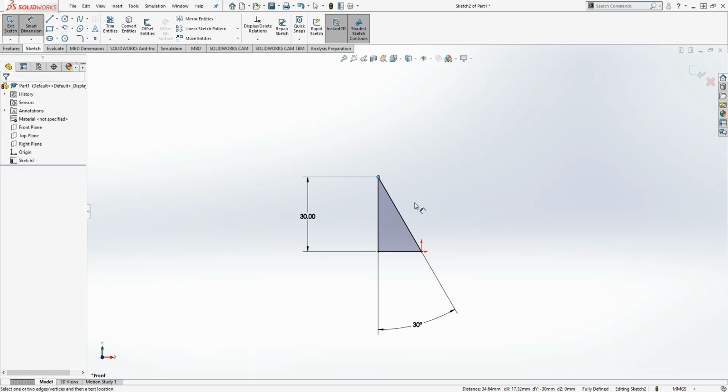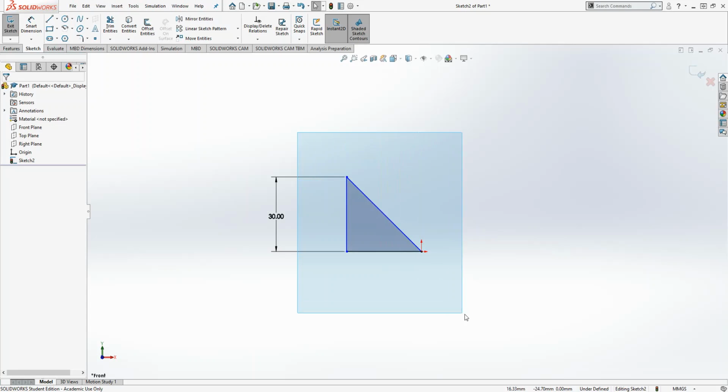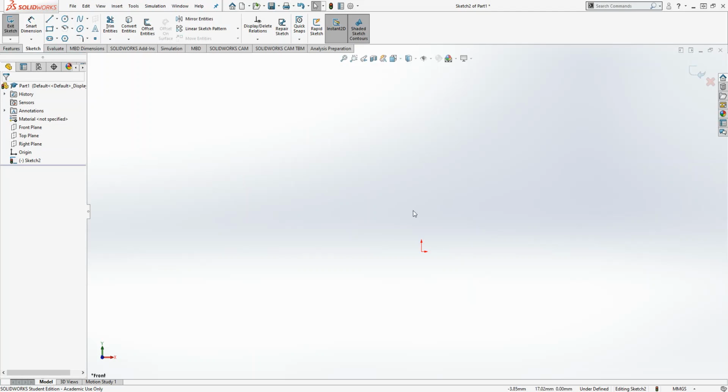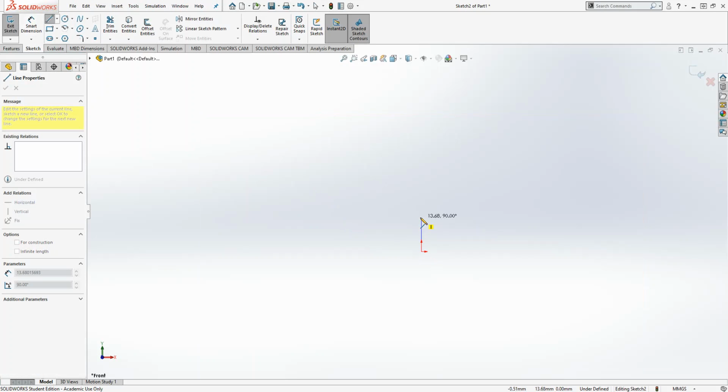And so what you can do is you can use this process to kind of define different things. You could define distances between points. There's all sorts of little things you could do with the Smart Dimension tool. Right, see now I could define the distance between points, not necessarily the length of the line. Right, so as an engineering tool this is very useful to define exactly how big your part is, right? If you're working on trying to make sure a certain bolt or a certain screw has to fit in with each other, you got to make sure these measurements are correct, because everything is abstract in a SolidWorks part until you actually give measurements and define everything.